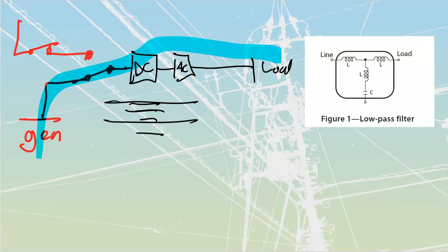You want to pick a low impedance. It needs to be high enough that it's still going to be significant, but low enough that it's not going to drop a lot of voltage before it gets through to your load. So about the 5% range is usually going to be suggested.